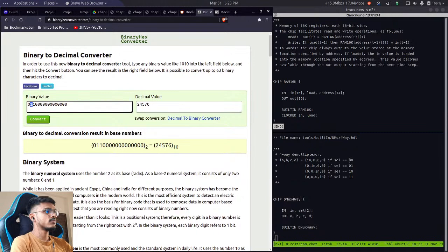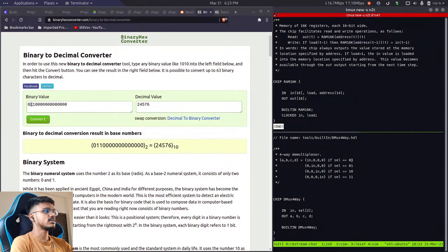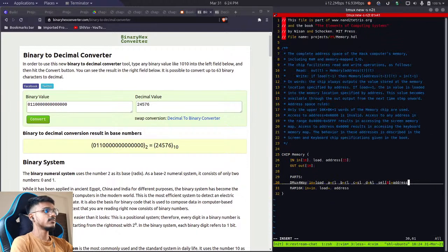I'm not sure if this is selected bit 0 or if this is, let's say if this bit is 0, then we can provide this address value. So we will see later. Right now let's pass 14th bit as selected bit 0 and address bit 13th will be selected bit 1. So I guess that is it for Demux.